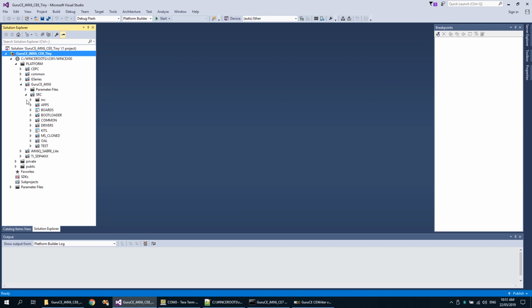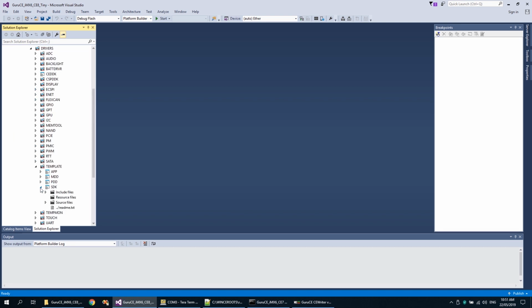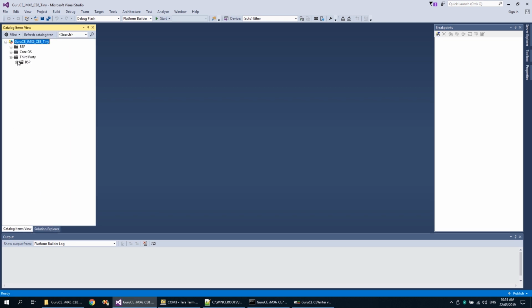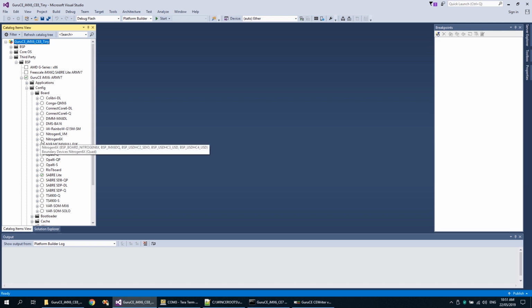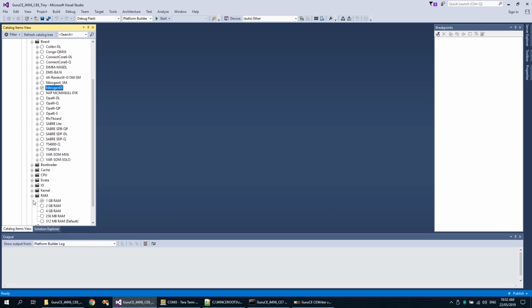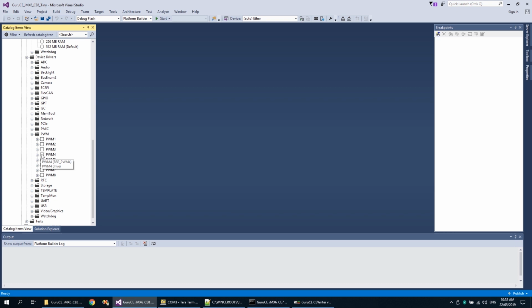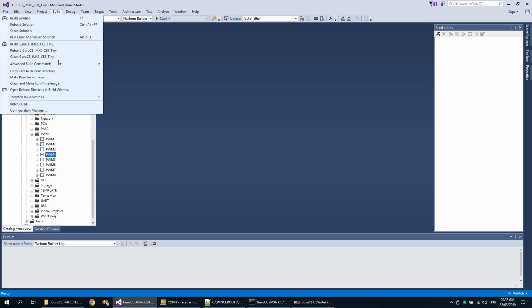The template driver contains functionality to read settings from the registry, map hardware I/O blocks, set up an interrupt handler and handle interrupts, and includes an SDK library and a sample application that uses that SDK to communicate with the driver. We quickly configure the OS design for the Nitrogen 6X board. Build it,